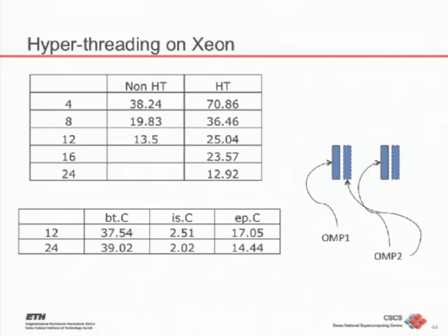So it says, well, now I switch in a second thread, okay, I'll give it these registers over here. It can now work on those, so when it does a context switch back, it doesn't have to do any of the dumping to memory. If it's only trying to switch between 2 threads, it just goes straight back to the other thread. You'll still get some software threading on top of this that the operating system wants to do, but from a hardware point of view, it can switch between 2 completely independent tasks in one cycle. And some people have generalized this to 4 threads, 8 threads, and so on.